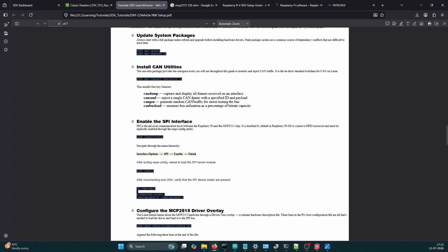Also, for a few of the things, in order to display and send some signals onto the bus, we would require this, and that's the reason we are installing it. Will you be able to do CAN communications with this too? The answer is no, because, as I explained in the beginning, it is the CAN module. This Raspberry Pi does not come with built-in CAN capabilities. So you are using the MCP2515 as a CAN module.